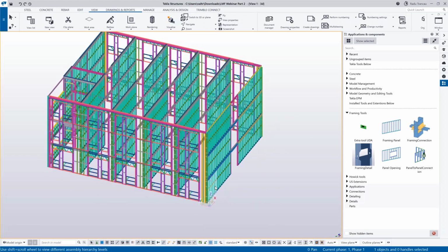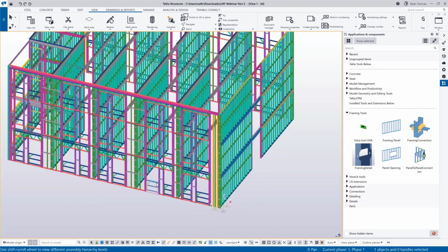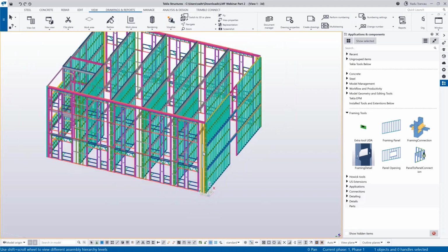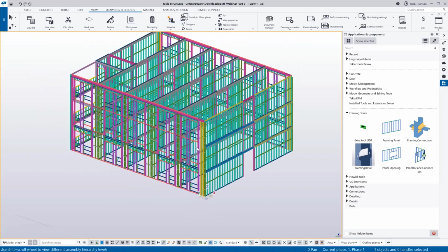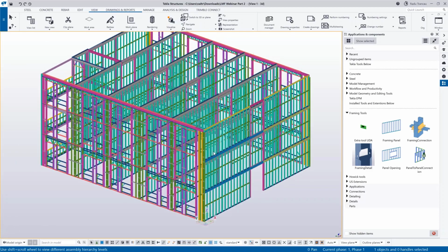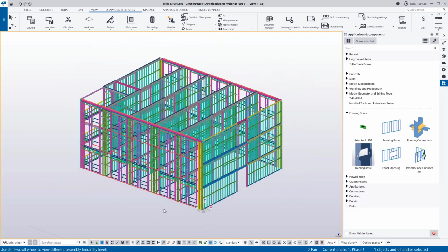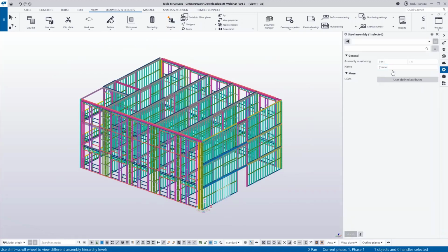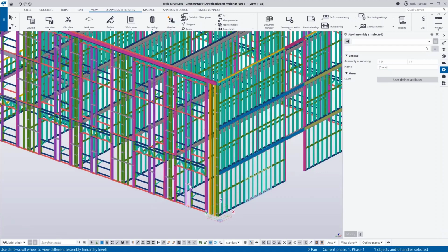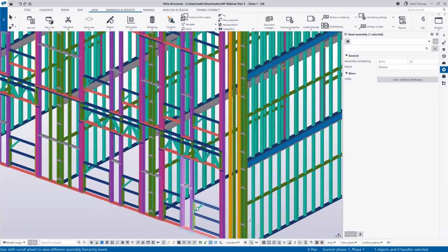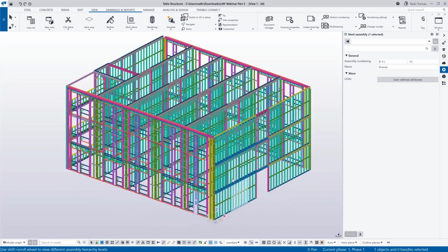The first thing is, if you're doing repetitive structures based on the same panel lengths, approximate grids, or approximately the same openings or drawings required, you can have this model completed with everything such as assemblies and connections, assembly numbering prefixes or series numbers, openings, and basically everything that you can reuse in a new model, along with drawings.